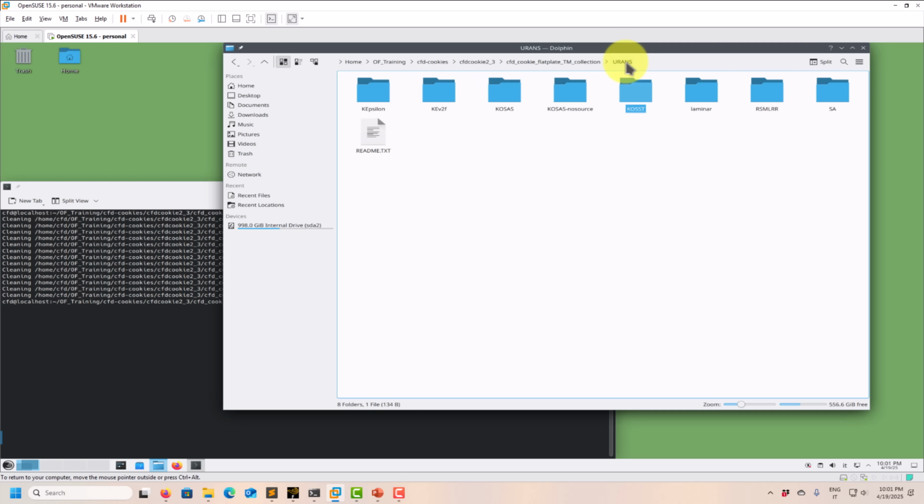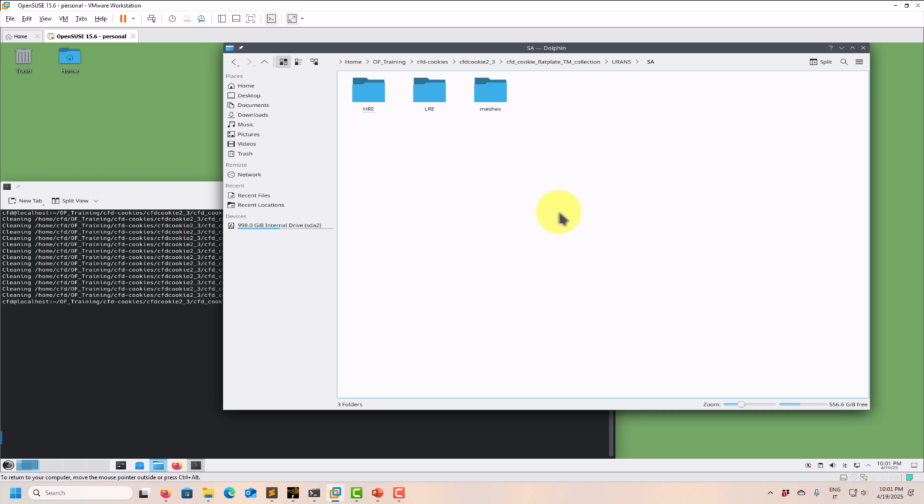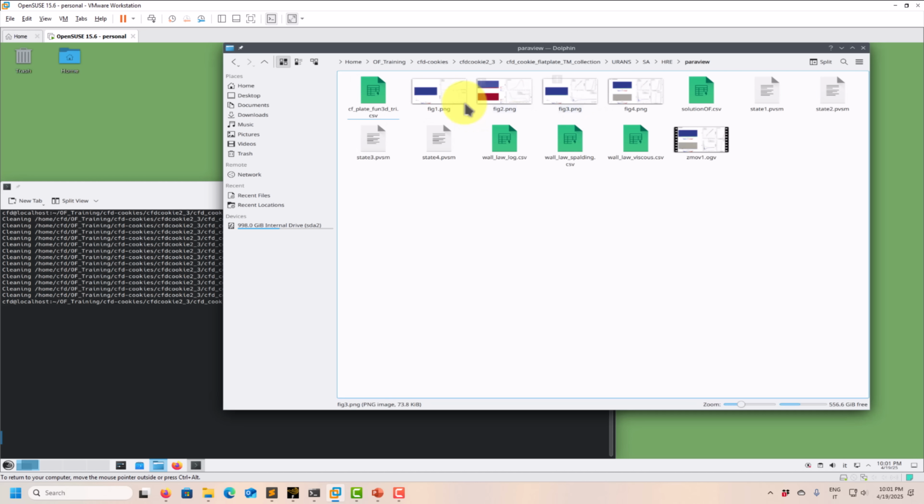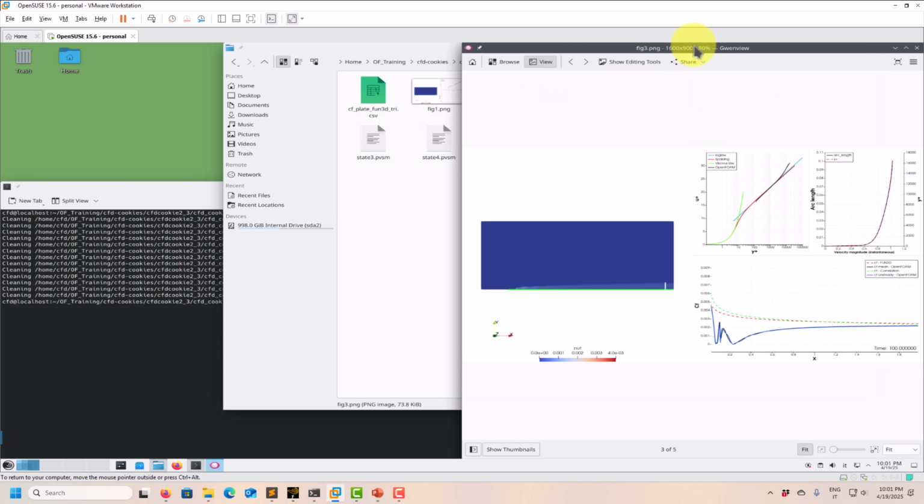Okay, so feel free to rerun this one. Remember, this is time consuming. The question, how long should I run? Well, you have it there. You look at your statistics, and it will be up to you to choose when to stop the simulation. And remember, this will generate a large amount of data. Okay, so be careful to deal with large amounts of data. And then let's go to the Spalart-Allmaras just to end this discussion.